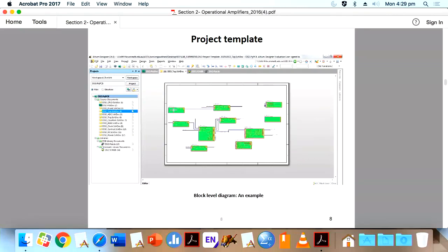So here you see, you don't need to literally connect it. You can name something here, maybe A, and then here you can say that okay, A is coming here. You know what I meant? You don't need to connect it, because sometimes that is not possible. When you have so many connections, it is not possible to literally connect from here to here. So you can just put it here and take it out, and define some name, VCCA or something, then you put one here and say VCCA is coming here, like that, when you have so many connections.